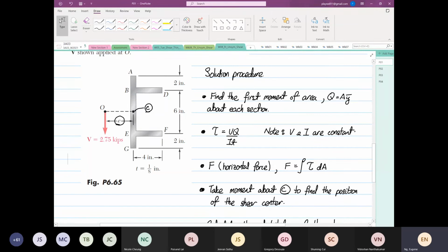If this were a thick wall, you don't need to do this procedure at all. And the answer is no. Any idea why? Is it because there's no horizontal force? No, there is horizontal force. Why? Because the walls are thicker, so they're not going to bend as much. You are almost there, Nathan.